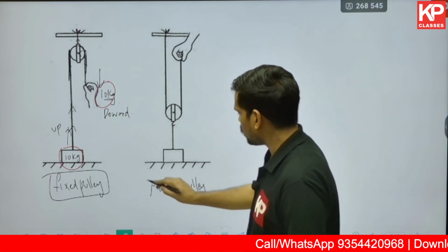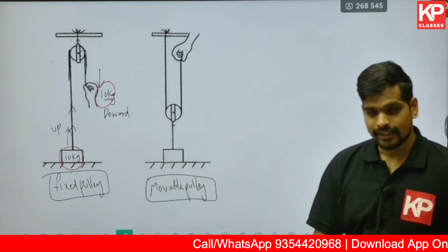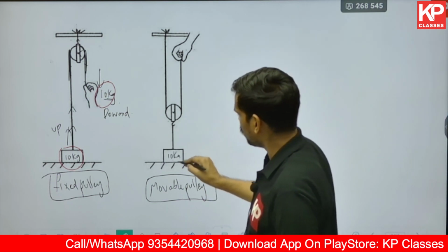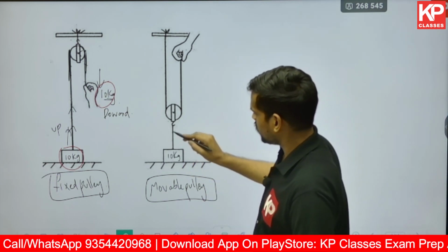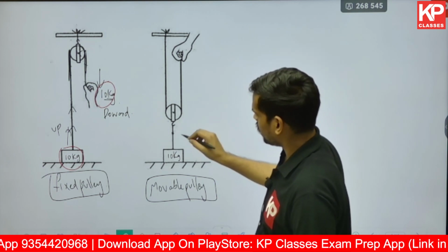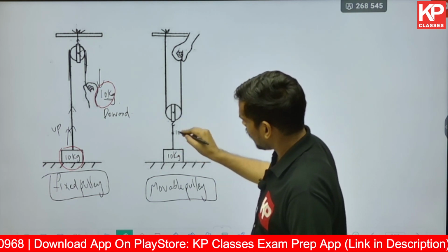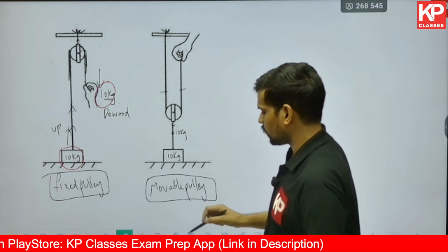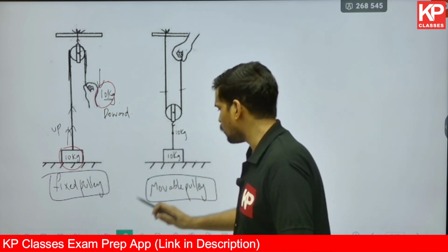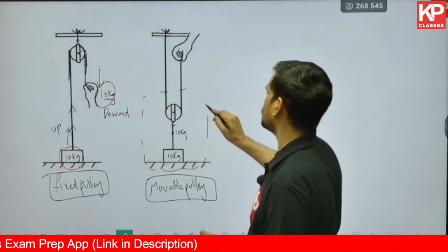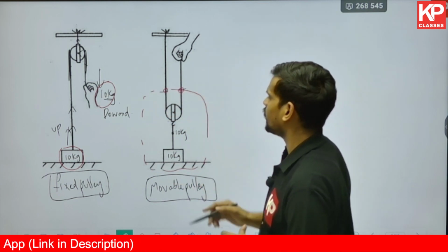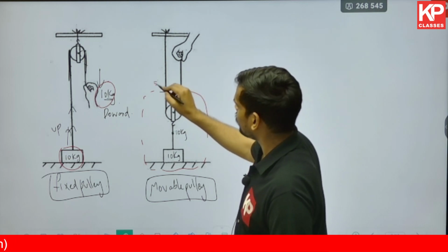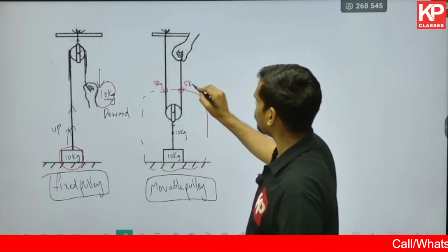And movable pulleys always add mechanical advantage in a system. So let us say for example this is a 10 kg load. The load in this particular connection over here, that is 10 kg, is being distributed into these two sides. In physics, this is called a free body diagram. If I draw a free body diagram of this part, there are two connections over here, cut into two threads. This 10 kg has to be equally divided. It is 5 kg over here, 5 kg over here.